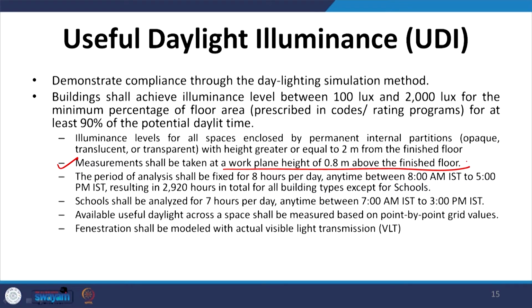Also, daylight should be calculated only for all the spaces enclosed by permanent internal partitions. They may be opaque, translucent or transparent, which have a height greater than or equal to 2 meter from the finished floor. The third is the period of analysis. It shall be fixed for 8 hours per day, any time between 8 am to 5 pm.